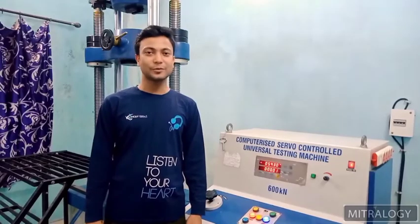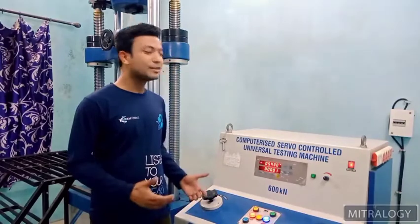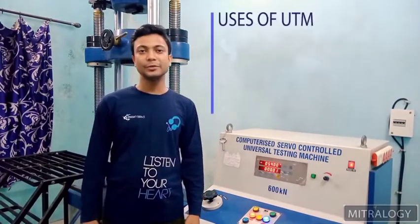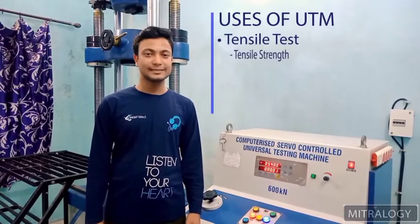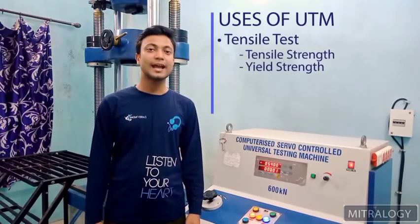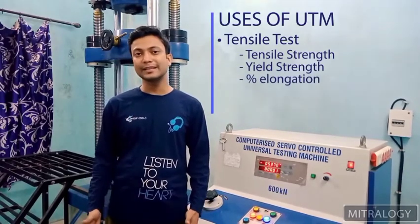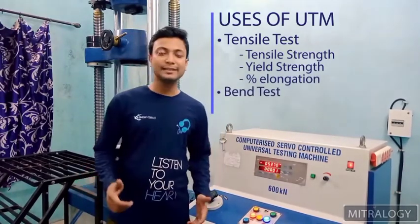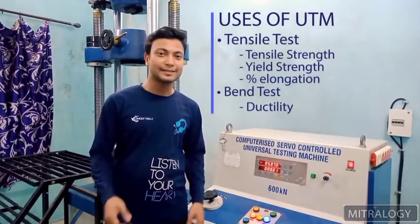Before showing you the components, I want to tell you what we can check in a universal testing machine. Mainly we can do the tensile test, by which we can measure tensile strength, yield strength and percentage elongation of the material. We can also check the bend test. By the bend test, we can measure or check the ductility of the material.